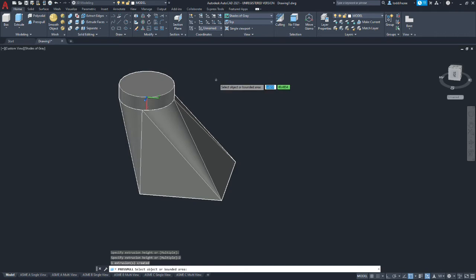Okay, so you could shell this like we have the other ones. I'm having trouble getting this model to shell. I can't get it to shell. I've tried for several hours. But I am going to show you another technique to derive what we want. And we are basically going to develop the same loft that's an 1/8 inch smaller.